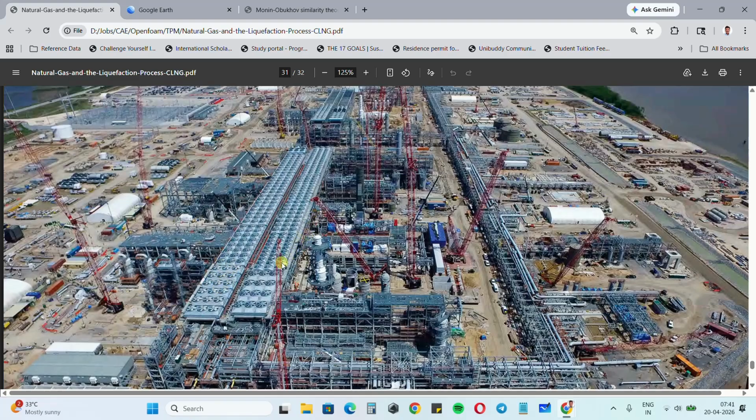The heat exchanger being at the heart of the process, we want to study how the hot air exhausted from the heat exchanger is recirculated in the region, and whether that recirculation is affecting the inlet temperature of the heat exchanger itself, and thereby the efficiency of the process.